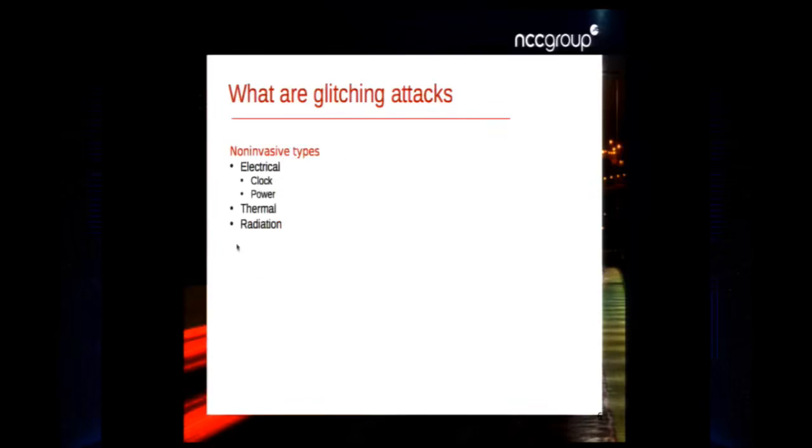With non-invasive types of attacks, we can do electrical glitching attacks, thermal or radiation attacks, and the scope of this talk is only going to cover the electrical attacks, which include the clock and power glitching variants.